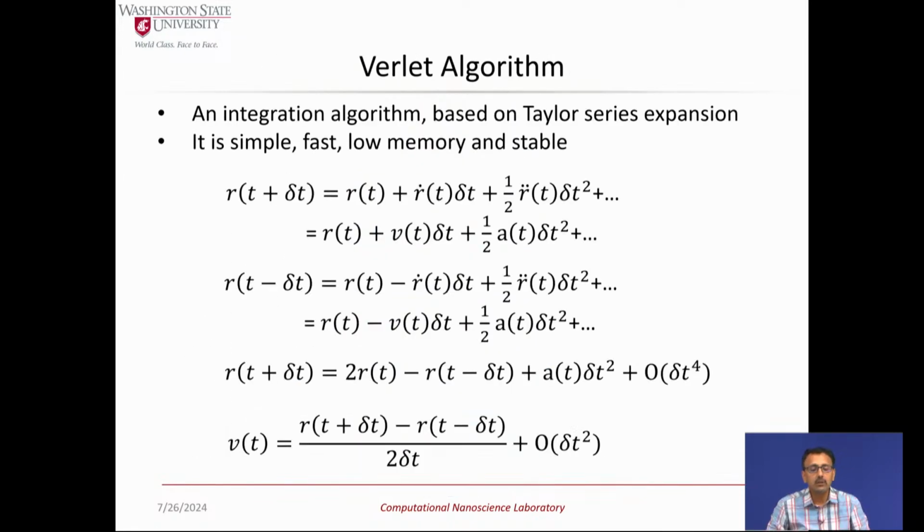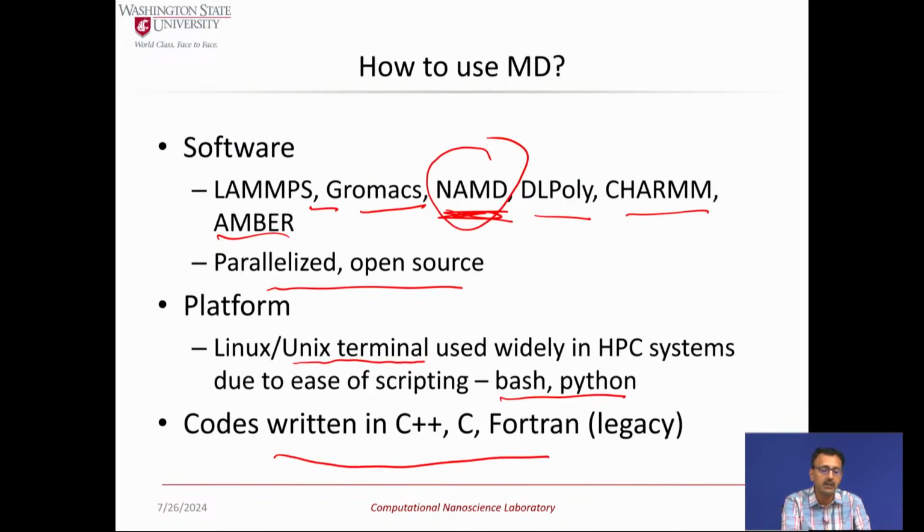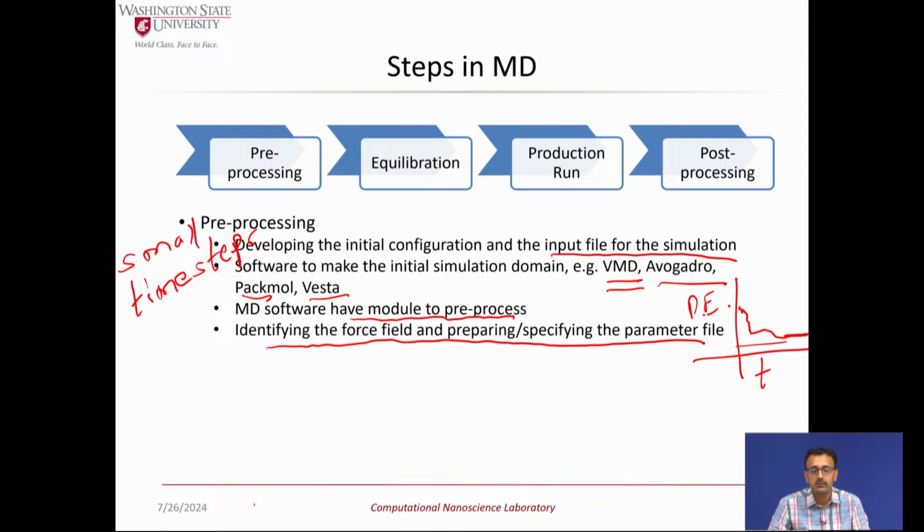So if you start with small delta t, the system can sometimes self-correct, in the sense that even if it has a very high acceleration because of a high force, due to some sort of error in the configuration, it can integrate the system to move towards a favorable state. So it's sensitive to this delta t, the time step for integration. That's one trick that you can often use for a rather tricky system to evolve it during equilibration.